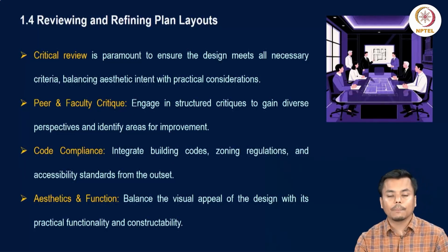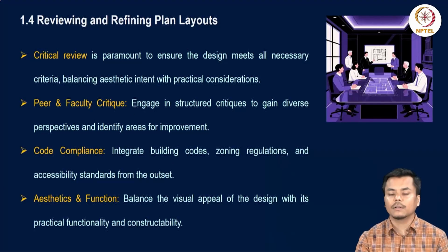Code compliance is very essential. What does the National Building Code suggest, or the DCR, that is the Development Control Rules of your respective state, suggest for the building typology? Based on that you can take inputs and incorporate them in the floor plan. Also, aesthetics and function, that is, balance the visual appeal of the design with its practical functionality and constructability.